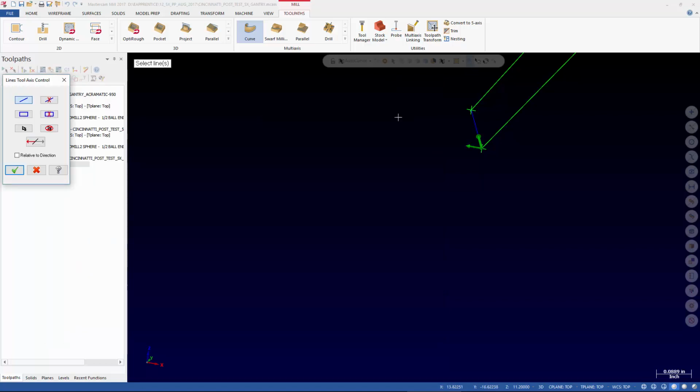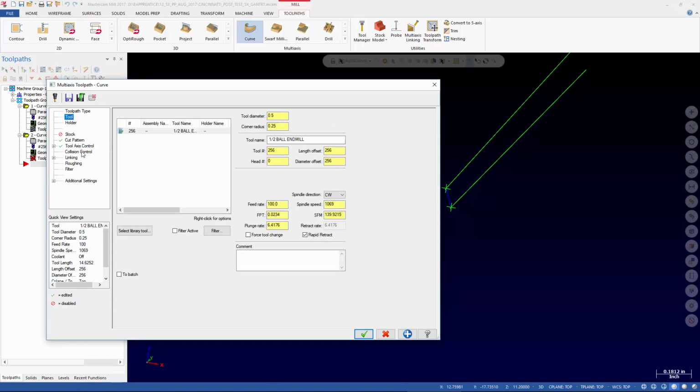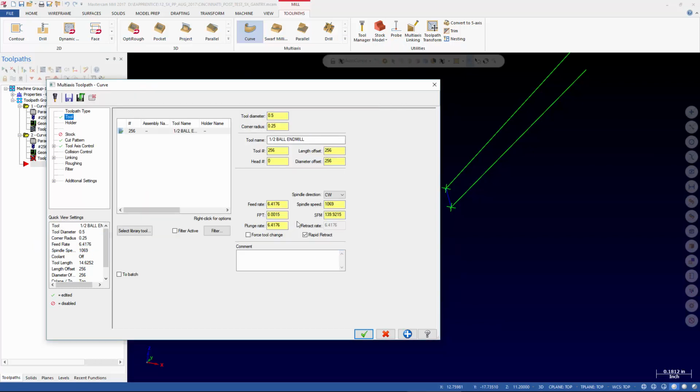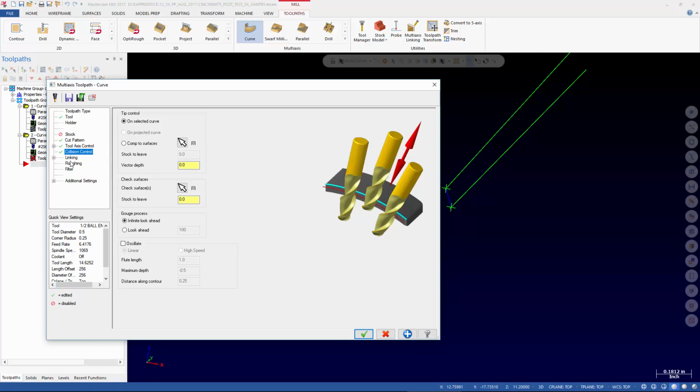So we'll use lines. We'll make sure those two lines are pointing away from the tip of the tool. In other words, back up towards the spindle. And I've still got my tool created with the gauge length of the tool so that we know the pivot length of the machine itself. All this stuff should be fine here. Let's get rid of the oscillate.